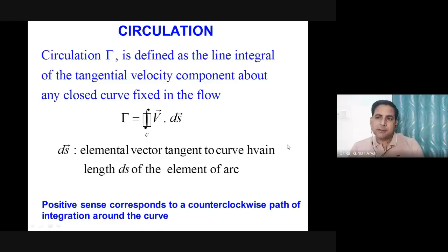And because you don't know what type of velocity profile it is, maybe parabolic or maybe a straight line. Straight line generally doesn't happen actually. So most of the time it is parabolic, half parabola or full parabola. So without knowing that much complication, most of the time people take the linear variation.